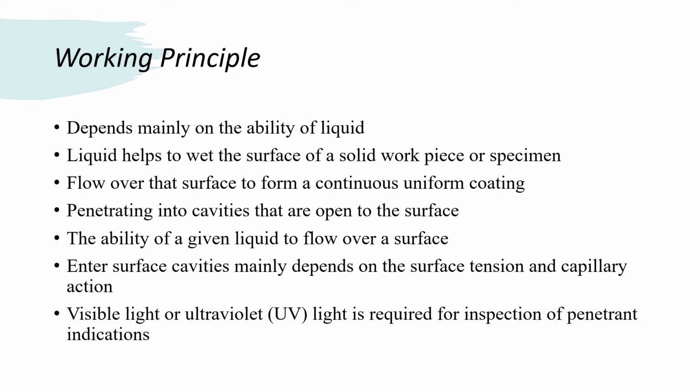The ability of a given liquid to flow over a surface and enter surface cavities mainly depends on the surface tension and the capillary action. So students, because of two things, one is surface tension and the second is capillary action, the liquid which is applied to find out the crack enters into the cavities.